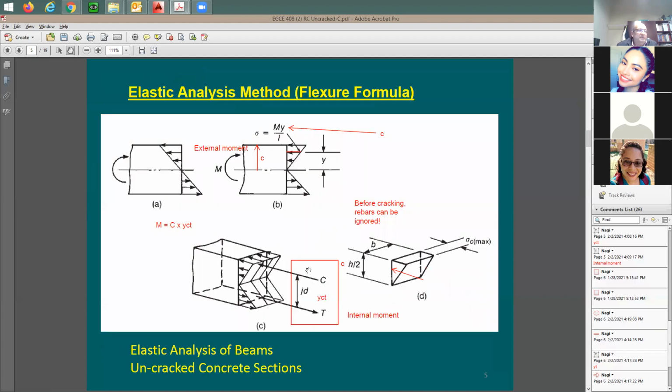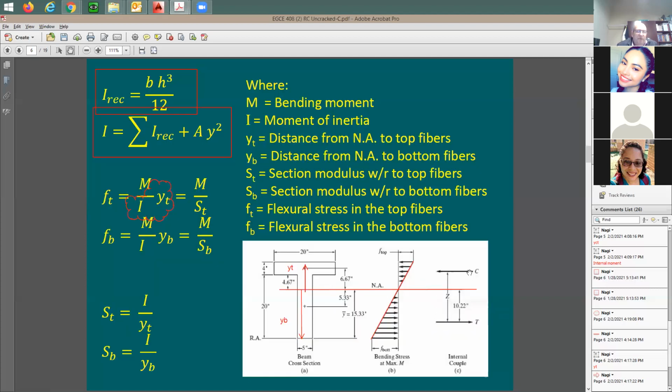Finding out these two forces is not really the flexural formula, but it is leading to it. You can find T and C, but once you start to do this, you have the force method, if you like. When you look here and see the stress on the top is different from the stress at the bottom, do I end up with C equal to the tension force T? I'm going to say yes, because equilibrium has to be satisfied. If you run your analysis given the stresses, find the stress on this T section and on this stem, and do integration, C is going to be equal to T at the end. This is confirmed.